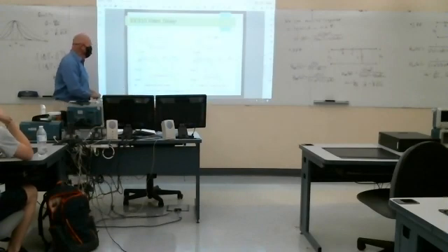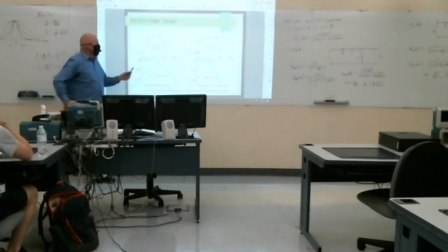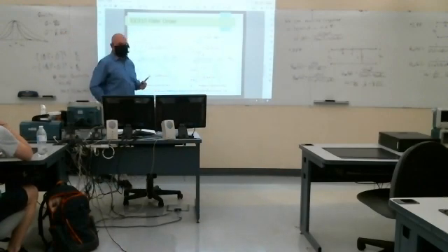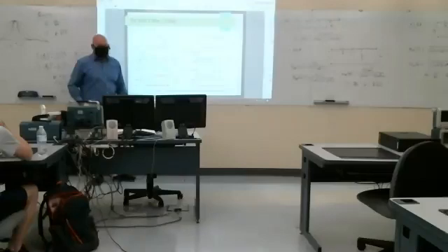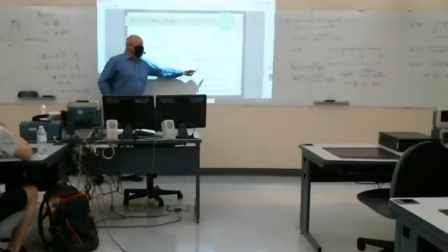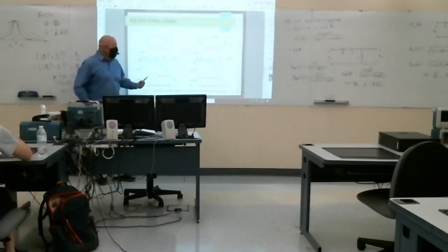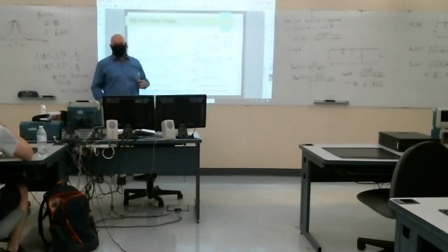And this figure is just showing a comparison of a simple RC low pass and a second order RLC low pass, and how you get the steeper roll off with the second order circuit, 40 dB per decade versus 20 dB per decade. And the disadvantage is you've got an extra component, so there's additional cost there.